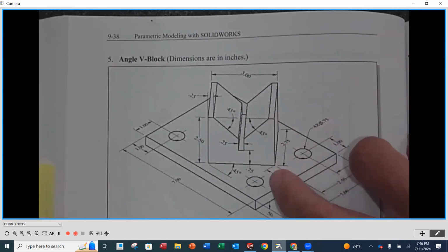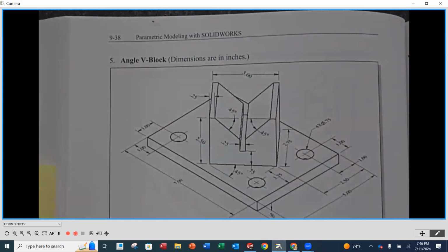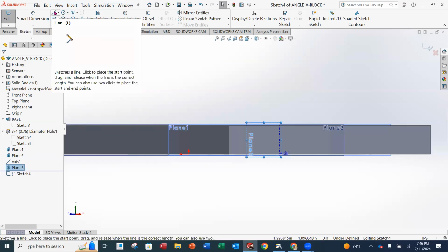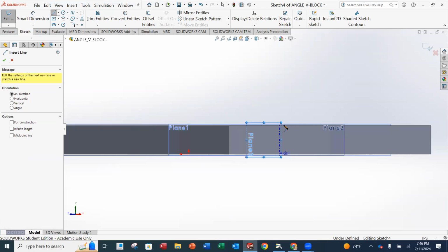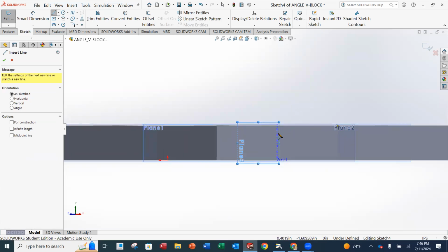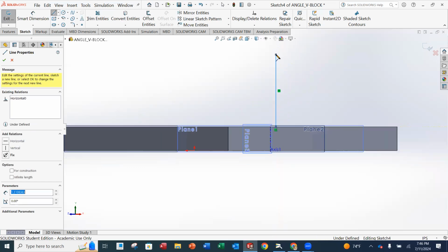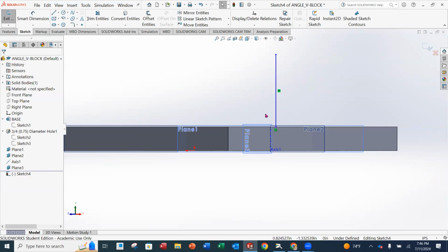Okay. So we are going to go to SolidWorks and create a line. I'm going to go above here, but not exactly over that axis. My axis is right there. I'm going to be offset intentionally to the right a little bit, and I'm just going to make a vertical line going straight up. Okay. And it's just a line.